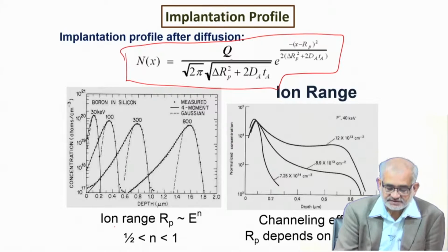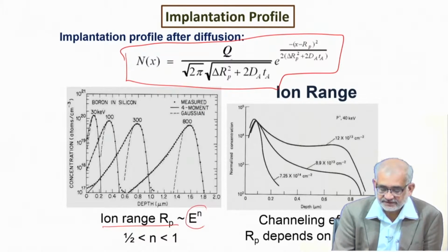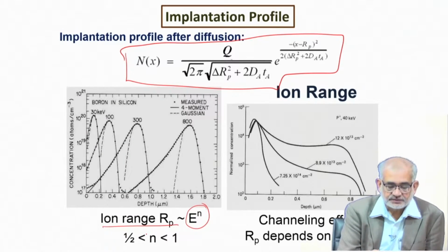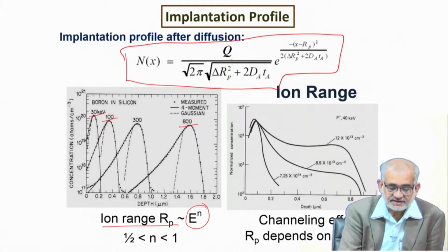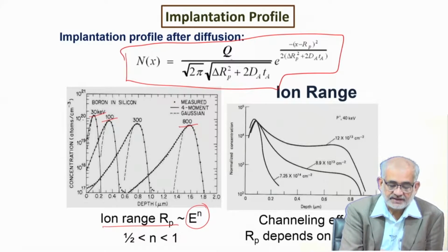Now what is interesting is that the ion range, the depth up to which the ions penetrate, will certainly be a function of the kinetic energy of the species. Now, as we increase the acceleration voltage from 30 kV to as high as 80 kV, what we see is that the concentration of ions, meaning the composition per unit volume, is not going to vary much.